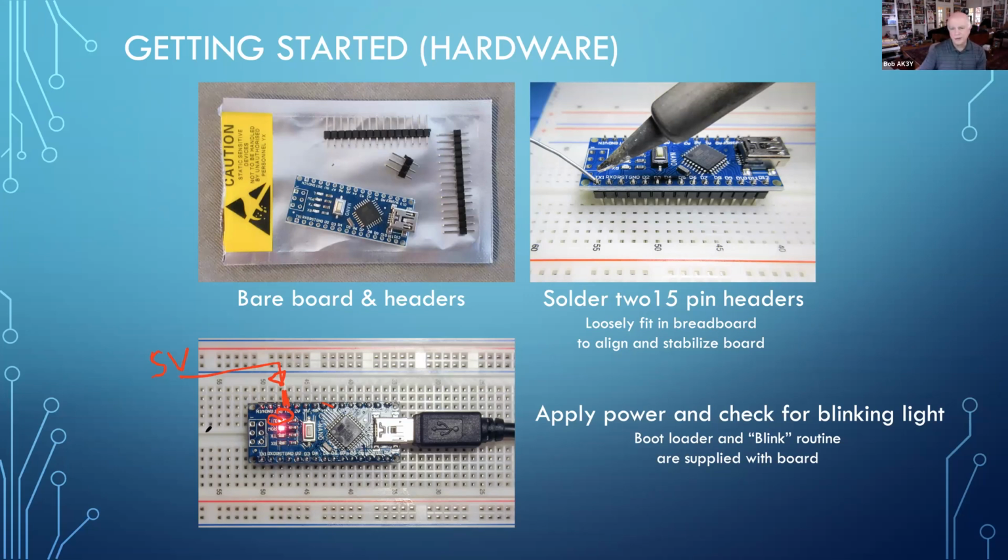And once you've done that, you know that you've wired it correctly because the microprocessor has now been checked out, at least is working. You may have a bad solder joint maybe to a digital pin, which you'll find out later, but at least you know that you've got power going to the microcontroller and the microcontroller is talking back to you.